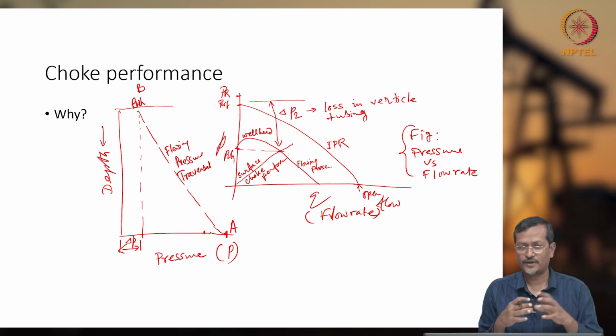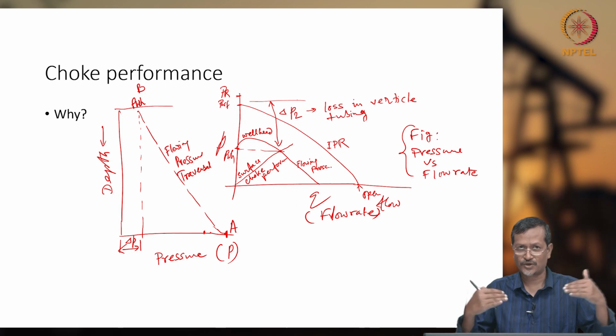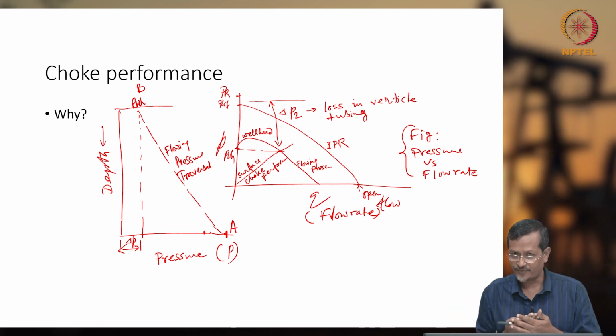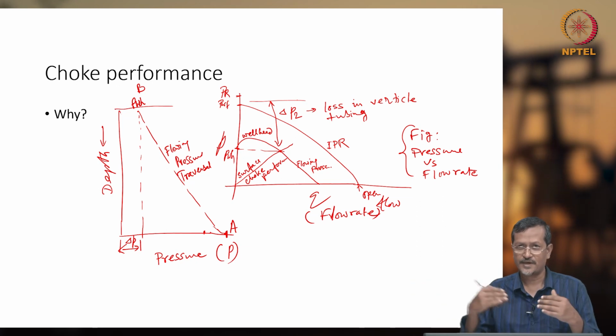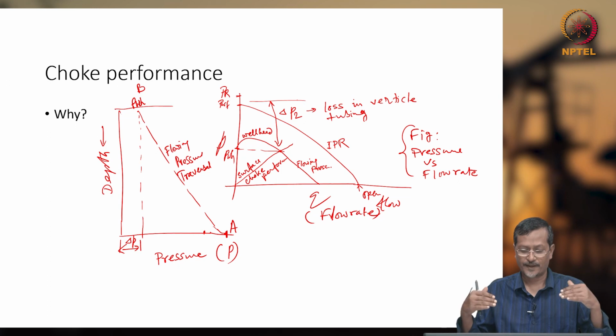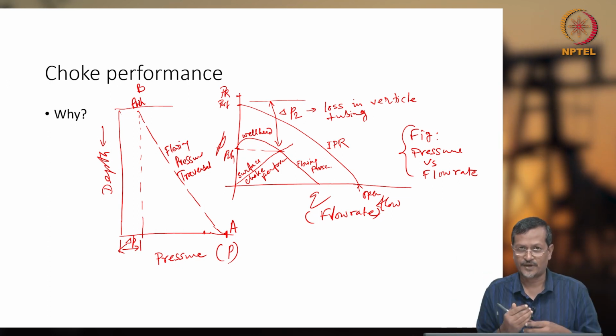And if you are getting, let's say, very high production today, and tomorrow because of sand injection or gas coning or water coning your production goes down, or maybe an artificial lifting system failure, or maybe the surface production system is not working, that will be costing huge. So your actual benefit will be lower. So your main target should be stable production for a longer period of time.